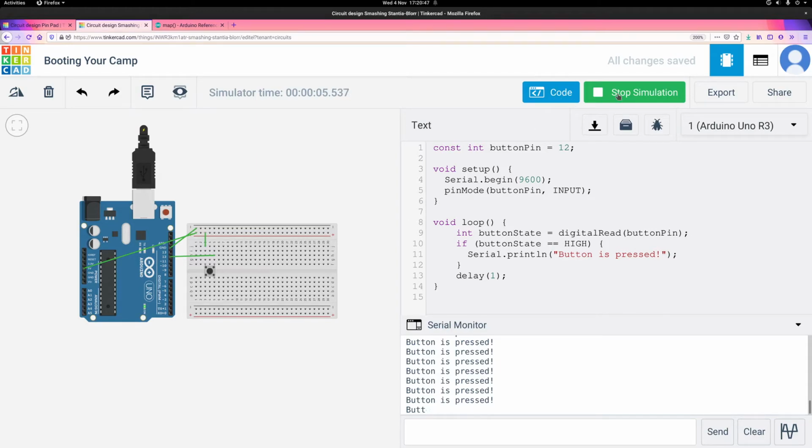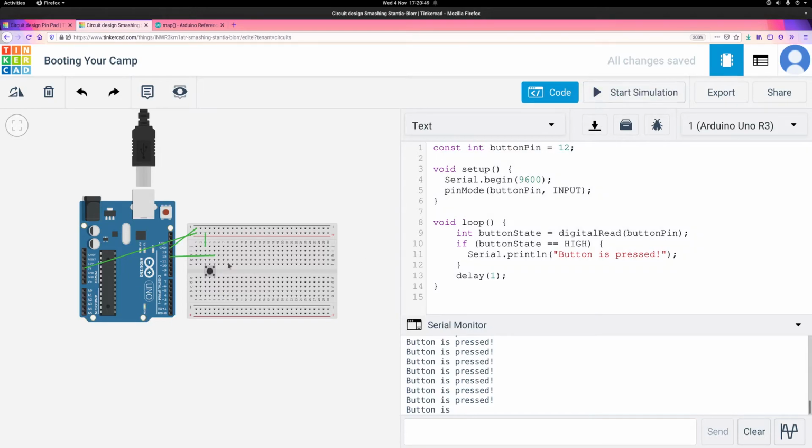So this is the issue that people often run into when they're very first playing with these buttons in Arduino, is that in this particular case, there's nothing really connected to this side of the button. Sure, it's connected to this pin here, pin 12, that does some reading. But when you put a pin into reading mode, this input mode, what it does is it effectively makes that pin act like a massive, massive, massive resistor. So it's almost as if there was nothing connected that electricity could flow into at all. So very, very little ever flows into the Arduino this way. And it has to be that way to measure voltages accurately.